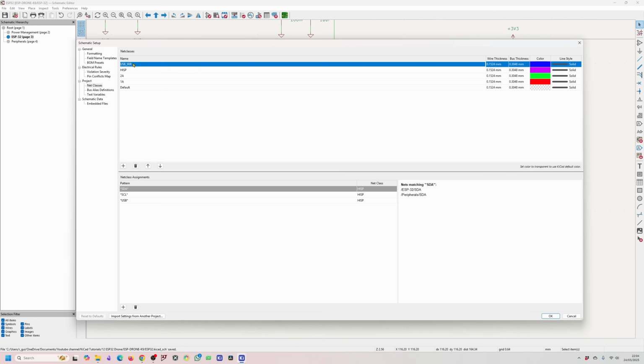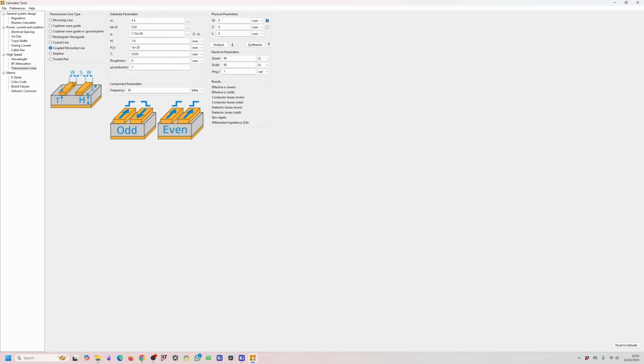Now, controlled impedance for 90 ohms basically means that you need to control the thickness of the tracks. So for a differential pair such as the USB line, you want to have control over the width of the track, the separation between the differential positive and the differential negative, and the height of the dielectric, basically where the next power plane is. So that might be a ground plane or a power plane.